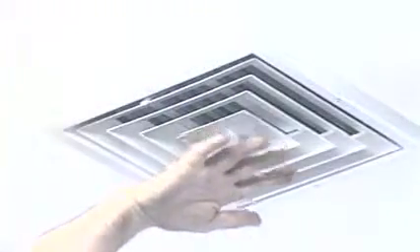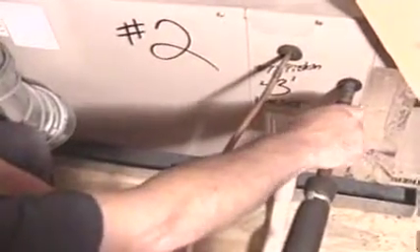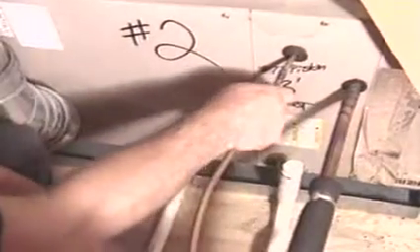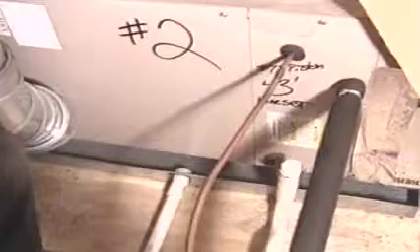The airflow is cool. Also check the suction line and the liquid line. The suction line feels cool and the discharge line feels warm, which indicates that the refrigerant system is absorbing and rejecting heat from the building. The root cause of this problem, the thing that caused the evaporator to ice up, seems pretty obvious.